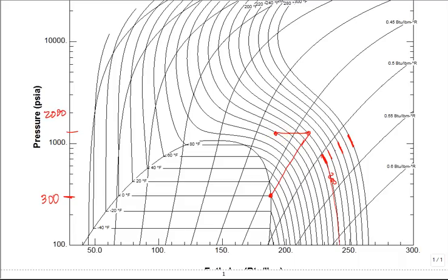Okay, now what do I do with this one? I want to put it through the expansion valve and do isenthalpic expansion, which is a straight line down. I've got myself a problem. I didn't get way over here where I have a high quality where I can get a lot of evaporative cooling with this CO2, did I? So what's the remedy? What's my design choice to do with this CO2?